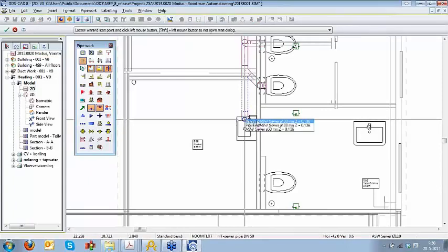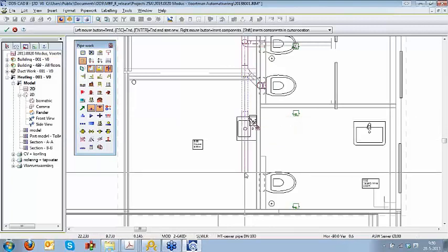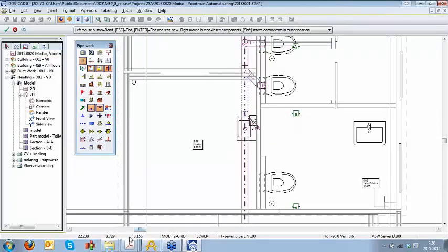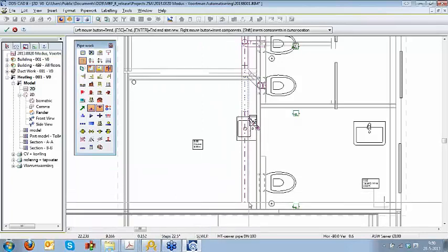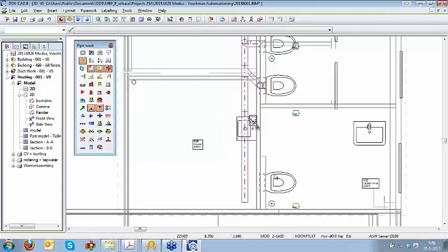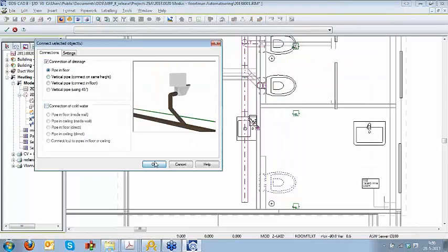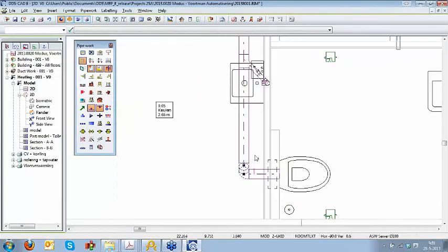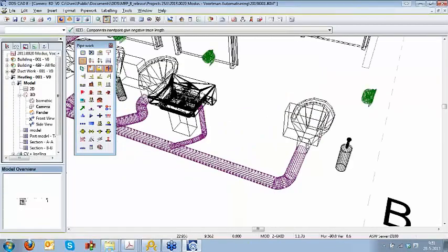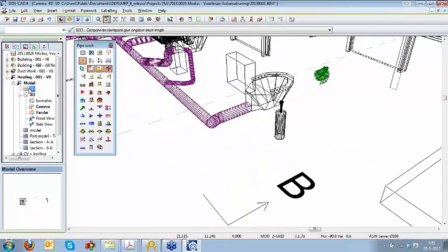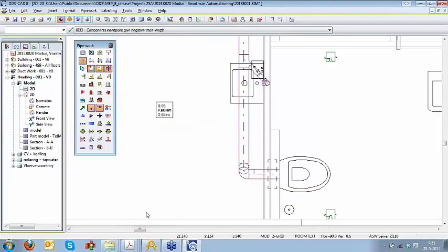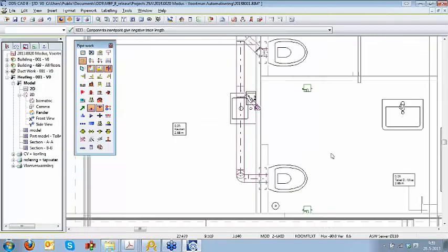So once more, making a connection from the endpoint, and because of the slope, this pipe will go up in our Z height, and such a connection, which we saw before with the automatic connection function with the floor pipe, will show me automatically that this pipe, because of the small overstack of the main string, is now changed to a bend. So this could be like an endpoint of our toilets. Well, there are many ways of connecting objects, and it is always up to the engineer to decide what is the best way for making a connection.